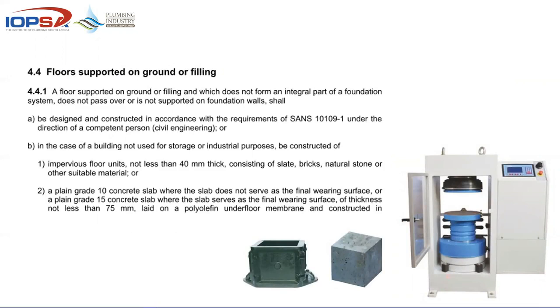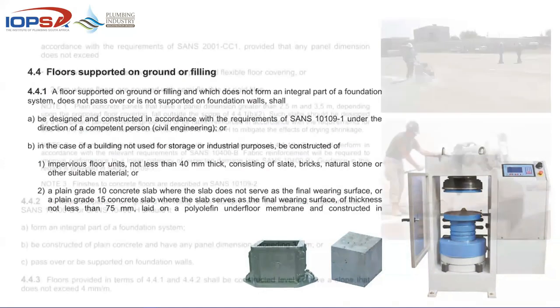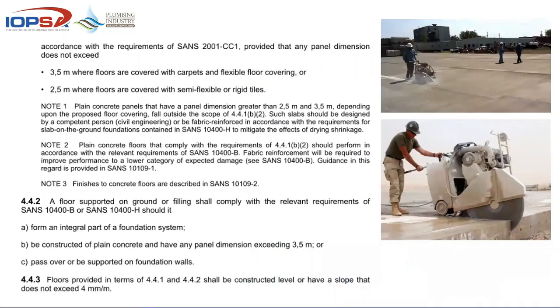Floor support, that would be your normal concrete flooring, and you'll find that it requires the concrete to be cube tested. In other words, the compressive strength after 28 days should be X amount per application, whether it be a floor, whether it be a foundation, whether it be a structural column. They all have their own requirements. So when it comes to plumbers and floors, etc., you'll find that there are more than enough tools of any size to make sure that we saw cut joints.